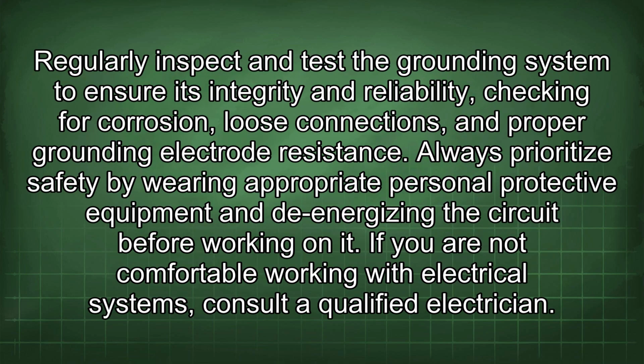Regularly inspect and test the grounding system to ensure its integrity and reliability, checking for corrosion, loose connections, and proper grounding electrode resistance. Always prioritize safety by wearing appropriate personal protective equipment and de-energizing the circuit before working on it. If you are not comfortable working with electrical systems, consult a qualified electrician.